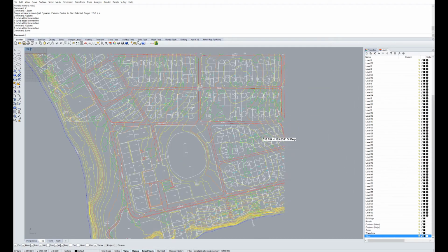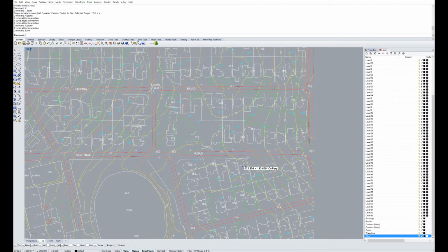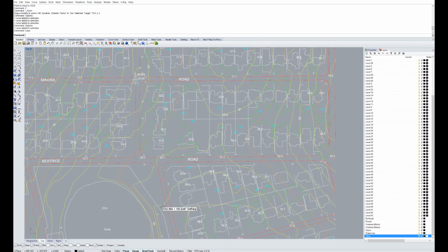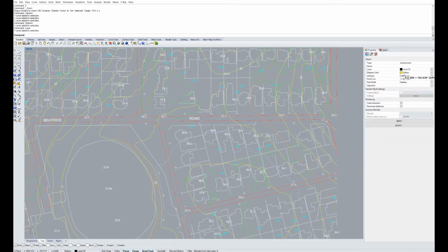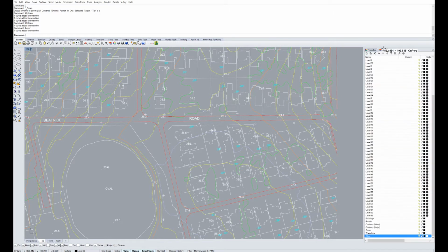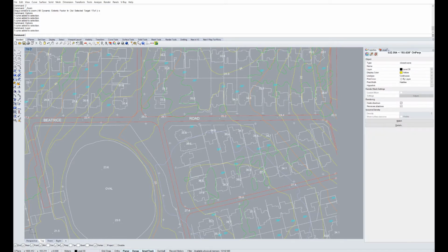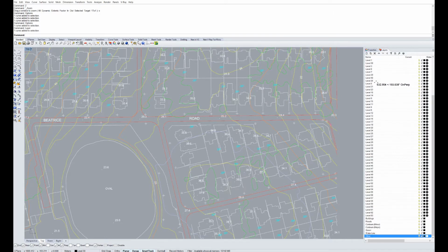And now whenever we click on layers, so for instance, let's click on this yellow line. If we select properties tab, under layer tab, we can see which layer it's on. So it's on level 30. So if we find level 30 in here, if we click on name, it'll sort them out alphabetically and numerically.